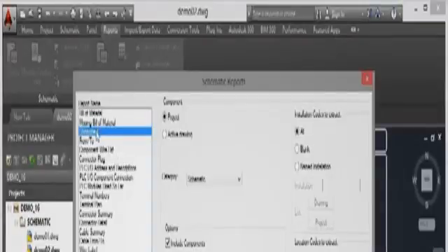We're going to go for the component report format here in the active drawing. Category will be schematic. We're going to include the children for the above components here and freshen the project database. I'm going to switch off the installation codes by making them both blank and the location code as well. And then I'm going to click on OK. That creates my report. Now you can see my report is fairly insubstantial. That's because there's not many listed catalogue components in this drawing Demo02.